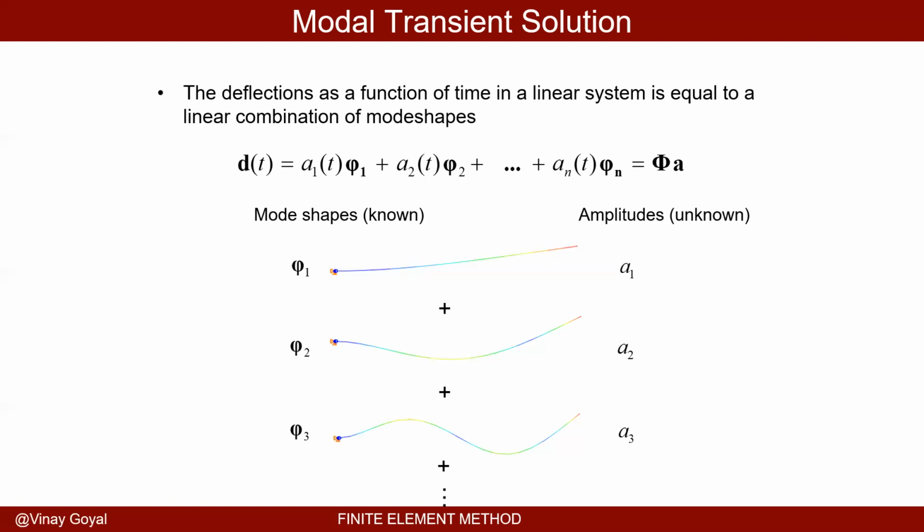Depends on how you go about that. Say you have a rocket or an airplane that has millions of degrees of freedom. Not all millions of degrees of freedom are going to contribute to the motion when a forcing function is applied. So you can make an assumption that maybe not all modes participate. I'll truncate it. I say, okay, I think all the modes up to phi3 are the ones that matter. I delete the rest of them and say that the deflection of that beam depends on these first 3 modes. In the beam example, I had 40 modes. I could say the first 3 are the ones that matter. So I could truncate how many of these modes I want to add up to get the total deflection of that beam.